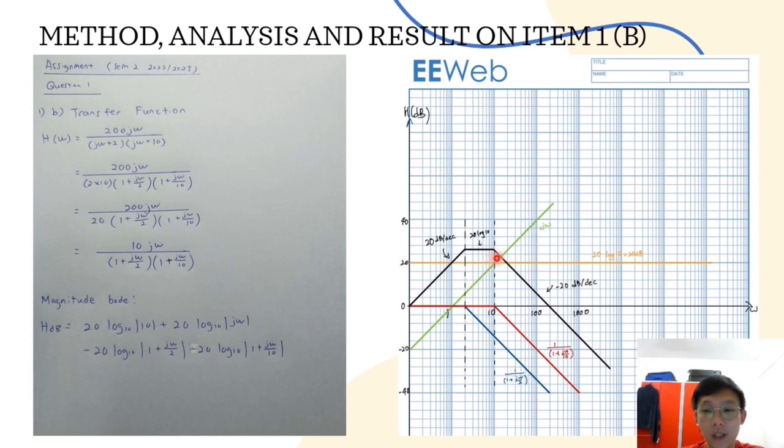So as you can see in the Bode plot semi-log paper, I already wrote the 20 dB per decade first here, and then the constant line is 0 dB because, as I said before, the green line represents 20 minus the blue line negative 20 becomes 0, and then straight down is the negative 20 dB, just like I mentioned the 20 in here, and then go downstairs until infinity or stop at any point.